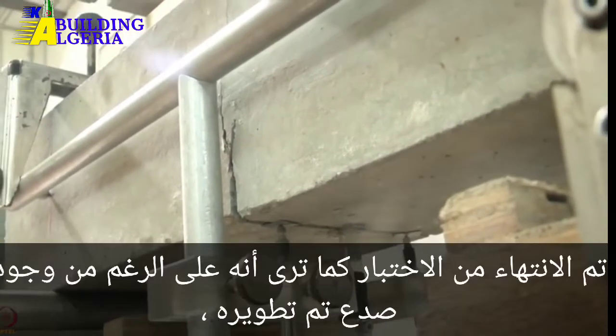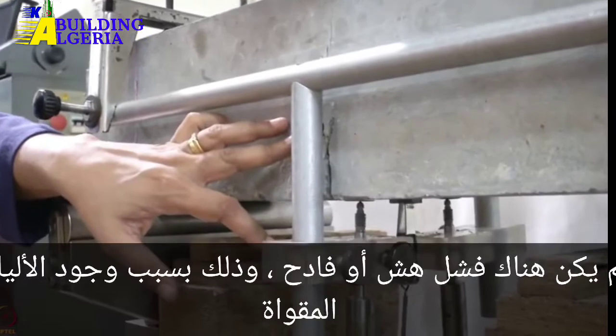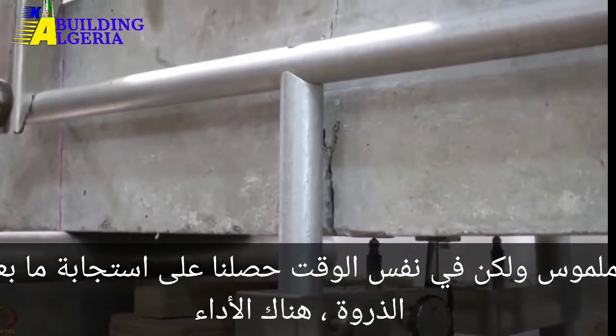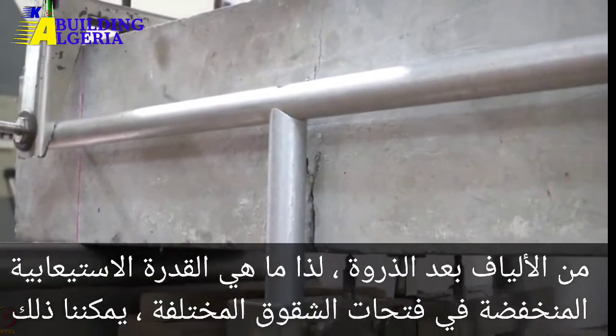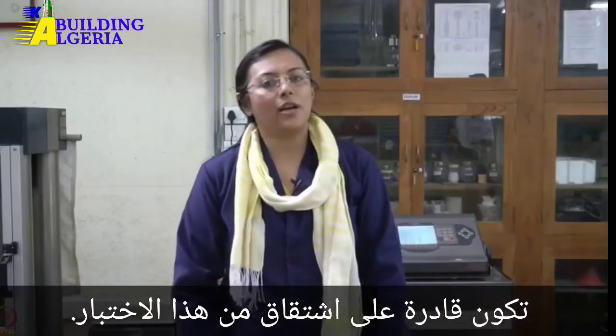Now the test is completed. As you can see, although there is a crack which has developed, there was no brittle or catastrophic failure. That's because of the presence of fiber reinforced concrete. But at the same time we have got the post peak response, that is the performance of fibers after peak. So what is the load carrying capacity at different crack openings, we are able to derive from this test. So now our test is complete.